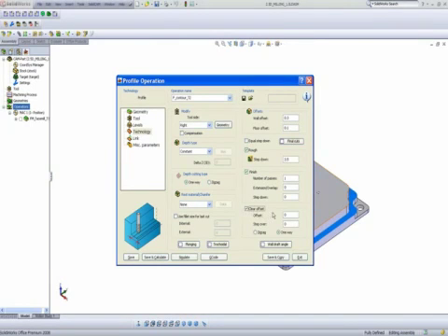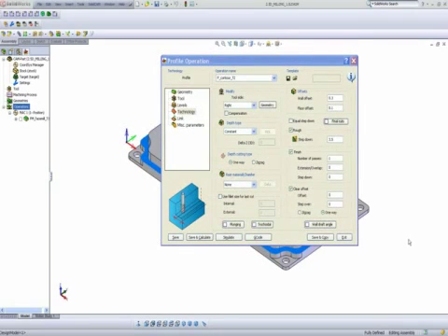In my clear offset, I can actually start further away from my wall and then work my way in. Now I'll choose my clear offset as being 4 millimeters. In other words, my first cut to be 4 millimeters away from the wall itself. And then my step over, how much should I go in every single time? I'll go in every 2 millimeters.